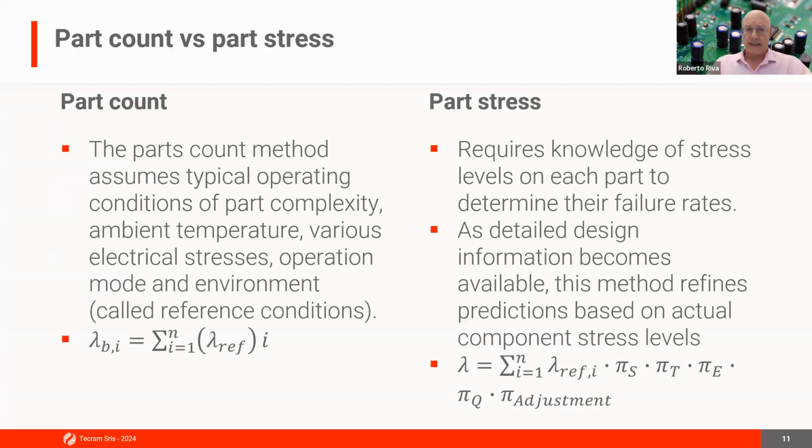And we will see what we mean by accurate, because we've analyzed not so much the entire BOM, which we did, but also we wanted to analyze different components with a different standard, and measure them against the manufacturer results, so that we would have some idea how far we were from the manufacturer prediction. So going back to MIL-217, part count analysis is a very simple one.